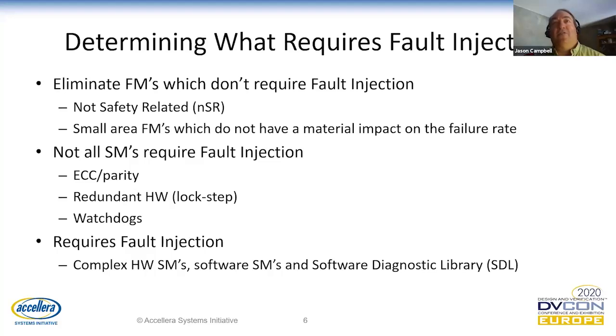and that will detect any failures. Let's say we have a software diagnostic library that computes an image checksum. We take a known image, run it through the software diagnostic library, get a checksum, and compare it to the known checksum. We do that every millisecond, or whatever is appropriate. And if we find a failure, then we know, aha, we've got a problem.